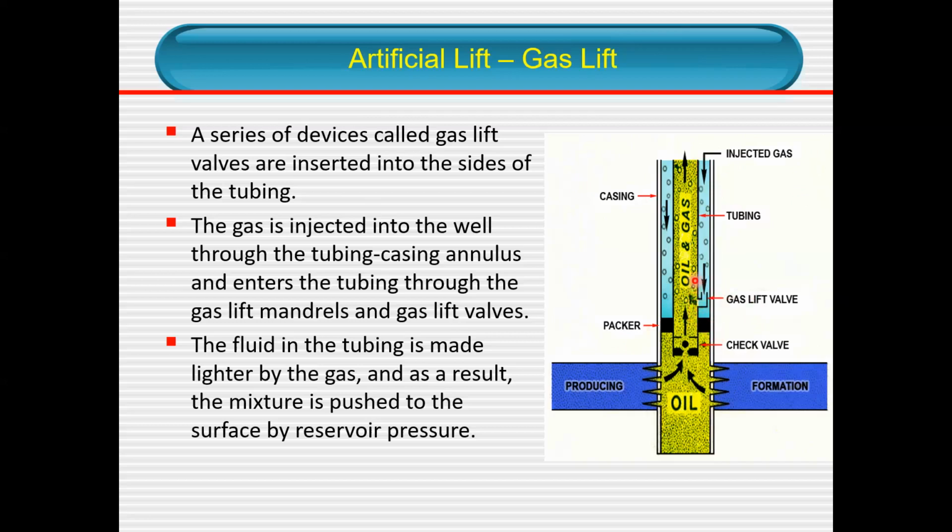And it is not only in a single place. It can be at several places, like even 3, 4, 5, 6 different gas lift valves at different locations, at different depths. And this has all been calculated, at what depth we are going to inject the gas, depending on the crude oil that is in the tubing flowing from the producing formation or reservoir.